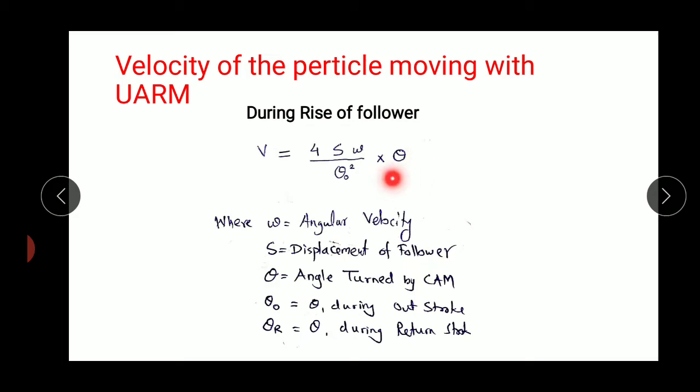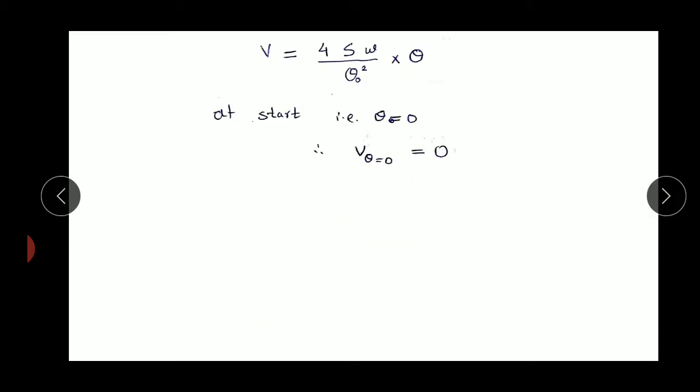So you can choose any angle during out stroke over here. Now it is represented like this. So at the start of the out stroke, the angle turned by the cam is 0. So you need to put angle turned by the cam as 0, that is theta equal to 0, keeping all these as constant, as displacement of the follower is constant, angular velocity is constant, and angle turned by the cam during out stroke is also constant. So theta is a variable over here.